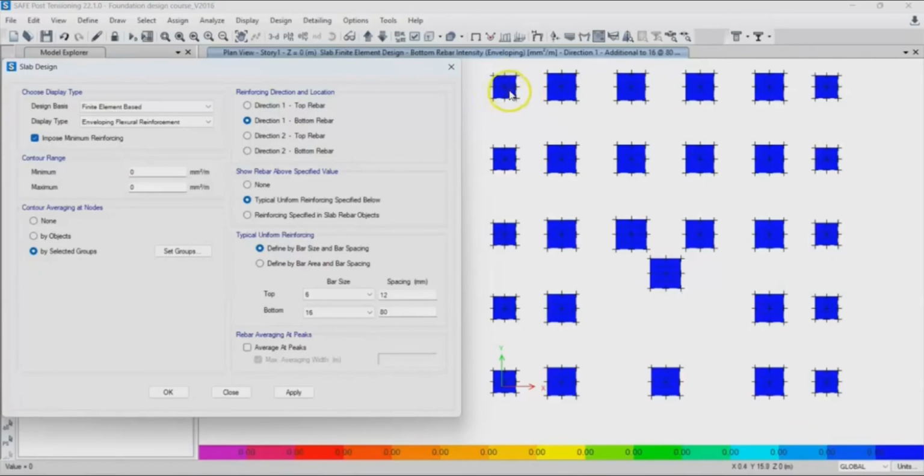obviously you need enough space to place the soil, because after digging out the soil and placing your reinforcement, you also need to refill the soil, right? But if the total area of the isolated footing is more than 50%, there is not enough space. So where will you place the dirt that was dug from the soil?